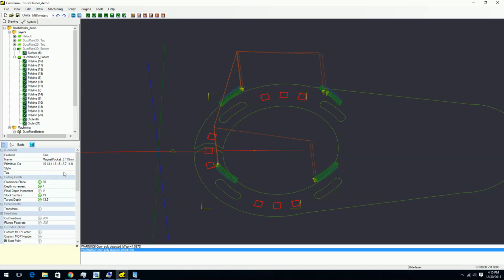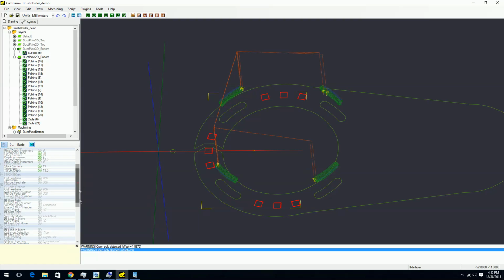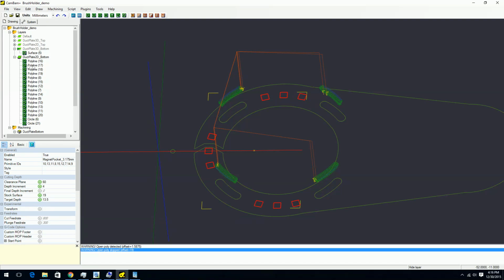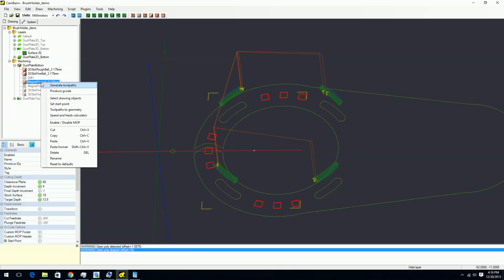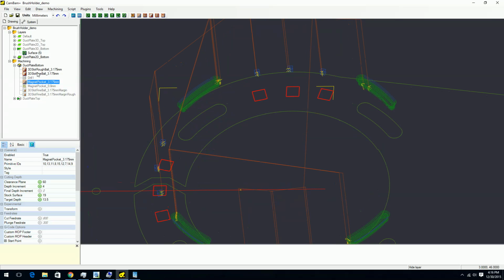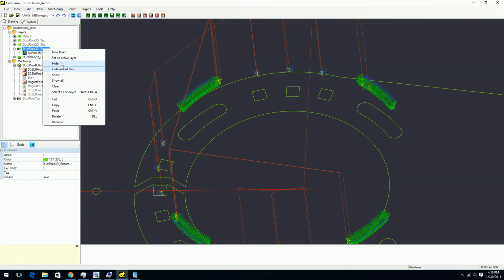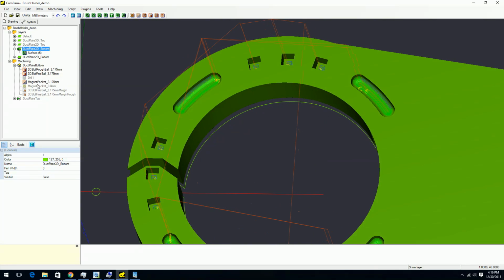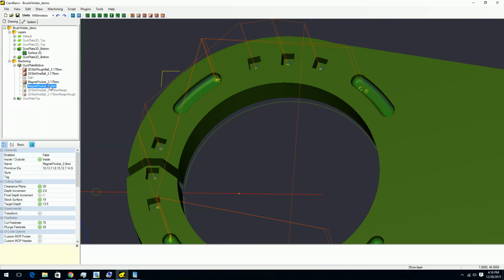So I'm using different masks here. They are highlighted here. I'm going by 4mm and my target depth is 13.5mm, and I'm using a 3.175mm V-carve bit here to do this. So this is going to be a very rough hole, and it will not actually give me square corners, because simply the bit is too big to create very square corners.